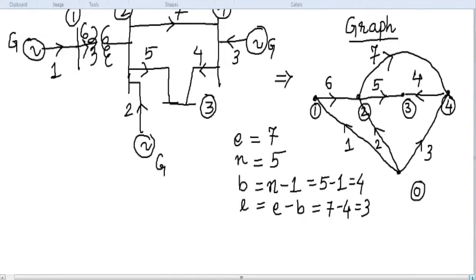Okay. So which elements are to be taken as branch and which elements are to be taken as link? We have already stated what are the conditions. Conditions are that when you select branch, then no closed path should be present and all the nodes should be present, and preferably try to check the condition that first elements are to be taken as branches or not.